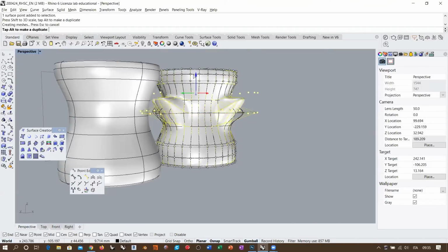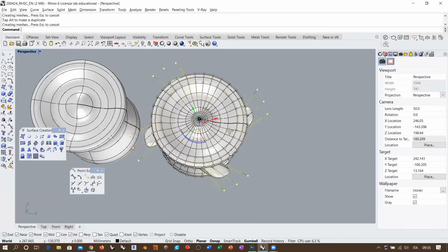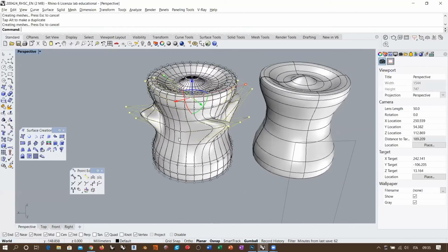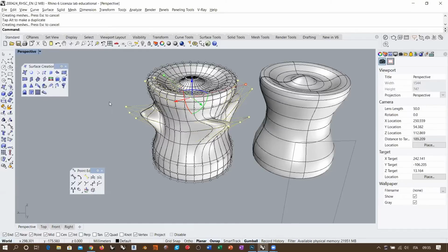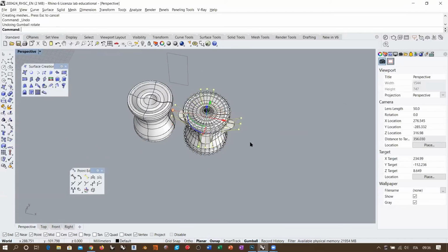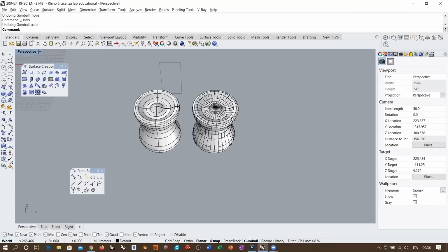Okay, so I can do whatever, basically. See how we are creating complex situations here, which would be extremely difficult to create with direct surface modeling? Direct surface modeling means that you create some construction lines and then you start trying with some sweeps or who knows what, right? But in this case, with topological deformation, it becomes very, very easy to create this kind of object. So this is the main difference when you create a deformable revolve surface.